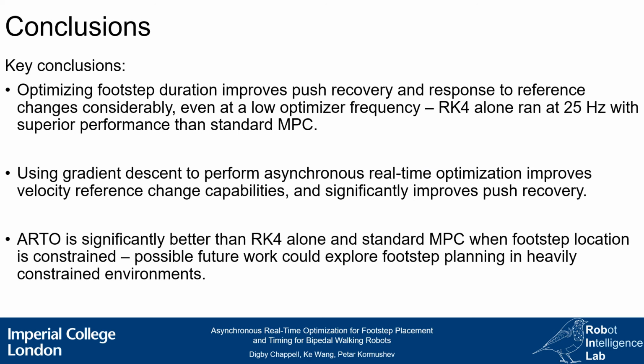Our key findings are this. Optimizing footstep duration greatly improves push recovery and response to reference velocity changes. Even RK4 running at 25 Hz was able to outperform MPC running at 500 Hz. Using gradient descent to interpolate between more accurate solutions improves velocity reference change capabilities and significantly improves push recovery. In particular, RTO is significantly better than RK4 or MPC when footstep location is constrained.